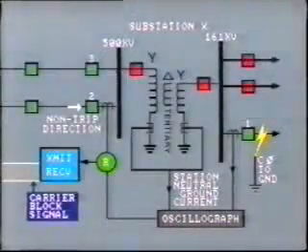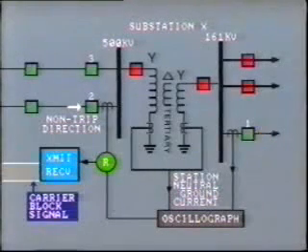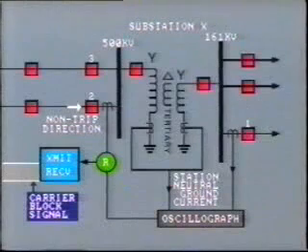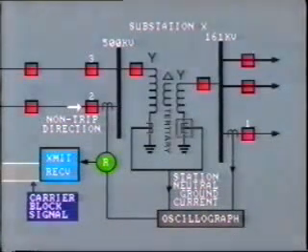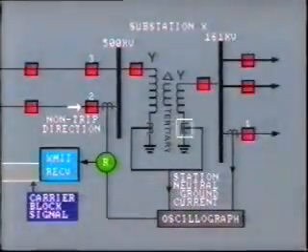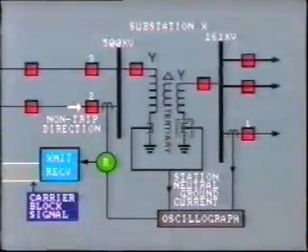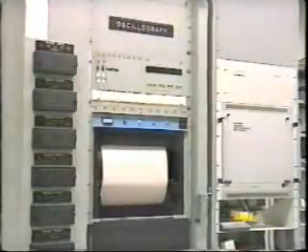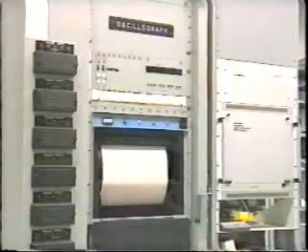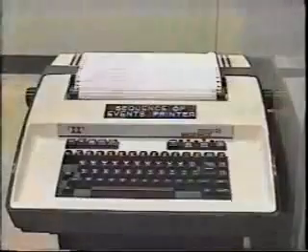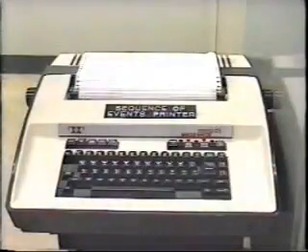As before, this was a temporary fault, so all breakers reclosed successfully at high speed. The problem was solved by replacing the 161 kV neutral CT with one having better operating characteristics. There are 2 basic methods for gathering fault data: automatic and manual. Fault data is recorded automatically on oscillograph machines and sequence of events recorders.